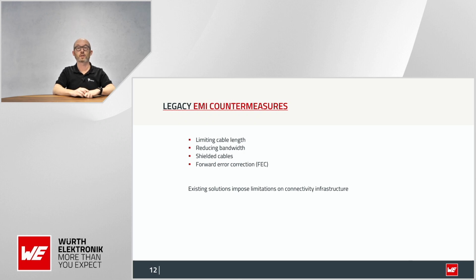We can apply shielded cables to keep out the noise and to work with the shield damping. But the shielded cables will degrade over lifetime. You can imagine when you have a camera mounted in the mirrors of the car and the cable is fed through the door. When the driver enters the car, he's opening the door, closing it, and after reaching the destination, getting out of the car, opening the door, closing it. So you have 4 times already per single ride where the shield is bent, and over a lifetime this can degrade significantly the shielding and also the insertion loss of the cable.